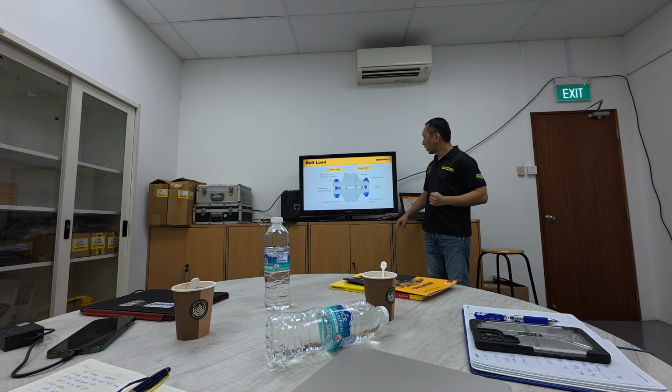And of course we need to know the force, if possible, that will act on the flange. What type of material is going through, what pressure is within the line, and of course there will be bolt load loss that may occur during the process, for example if it's a high temperature, or external forces. If, let's say, there are forces stretching the pipeline, these are things that we need to know.